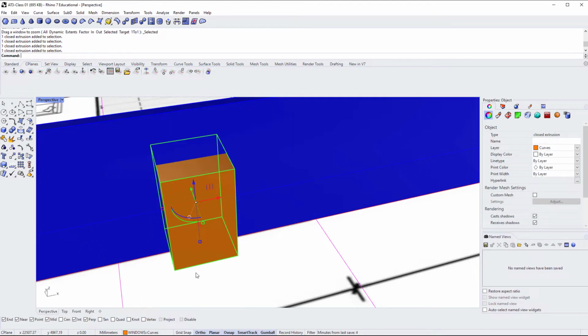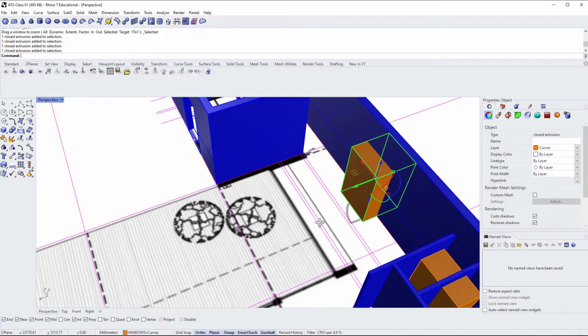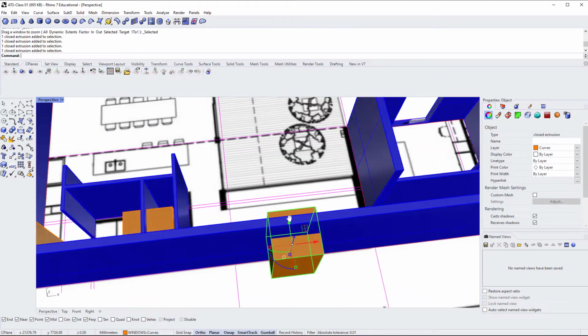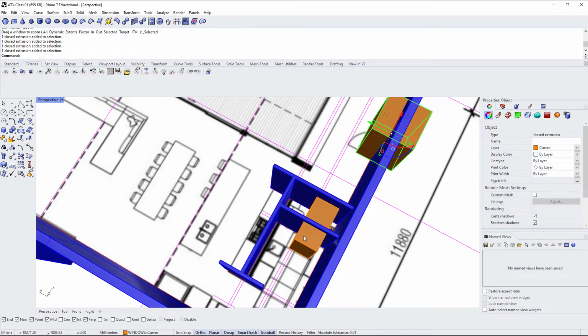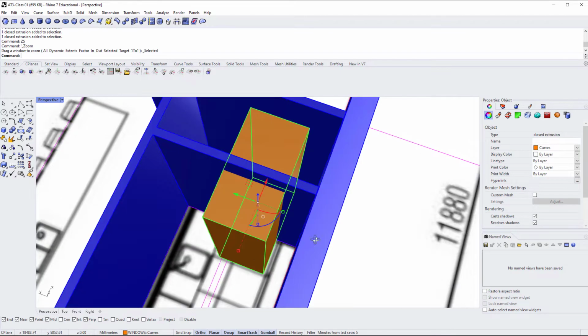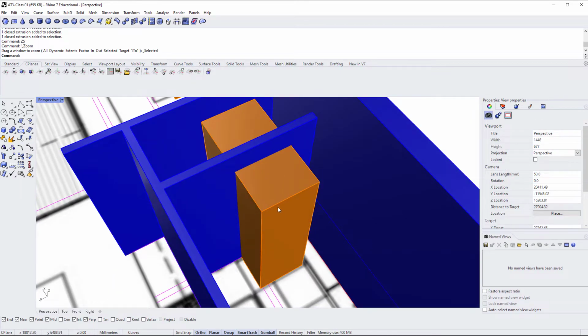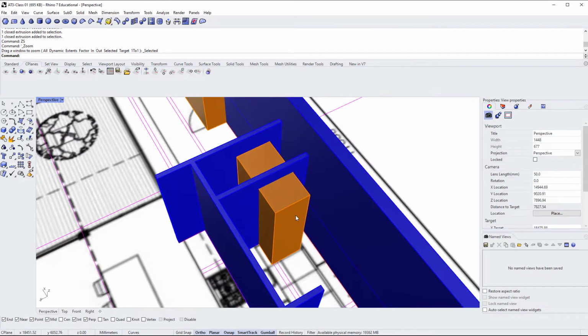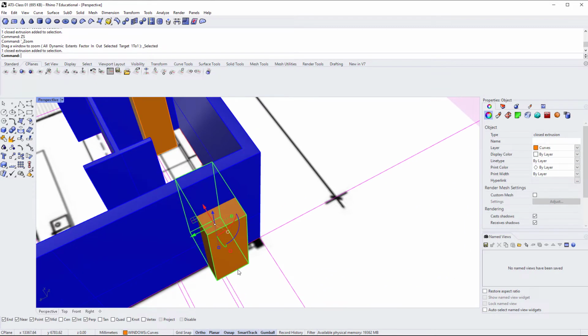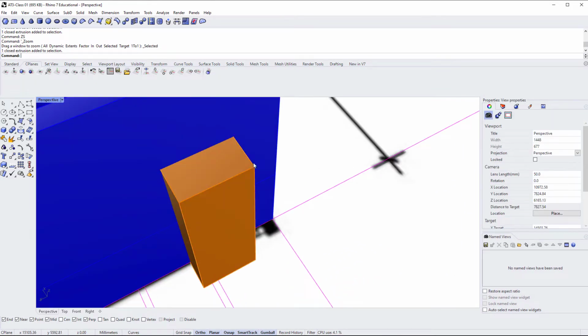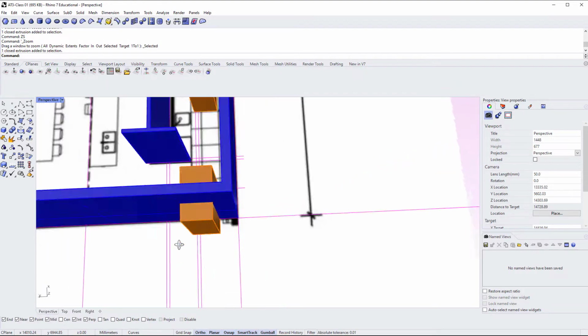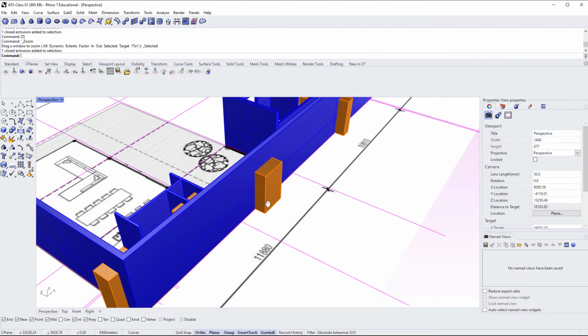The main front door is 1500 wide because you've got a 1100 or 1200 wide door plus a 300mm side light. And in the bathroom over here for this toilet, I have a 720 door, so it's a 790 wide box because you have to account for the frame. And then another 890 wide box for an 820 door at the laundry entrance.